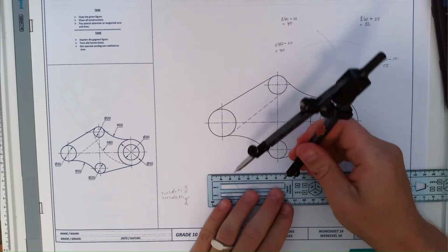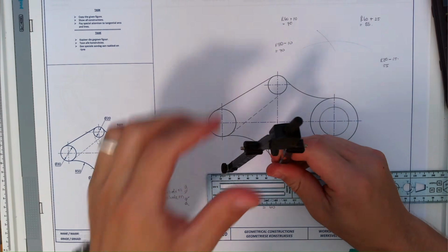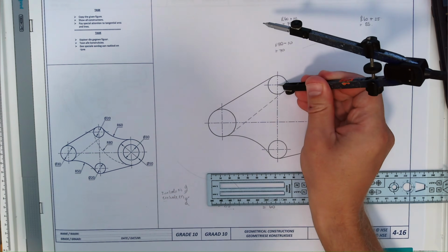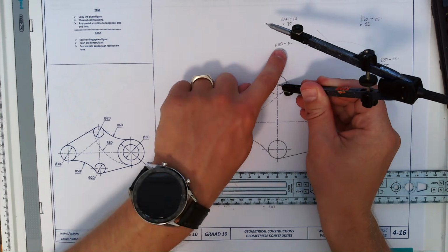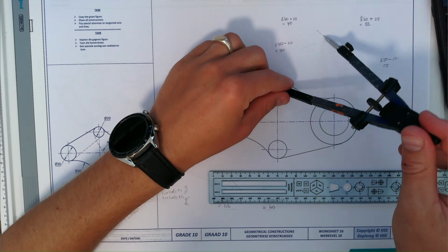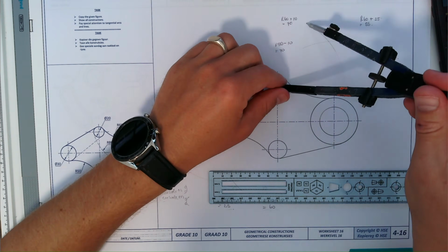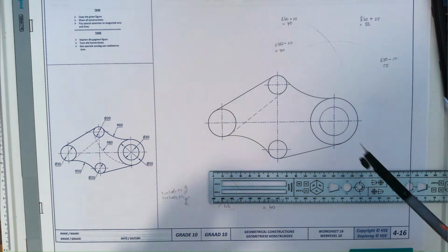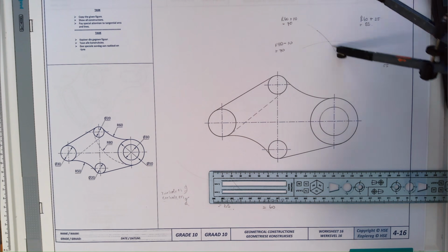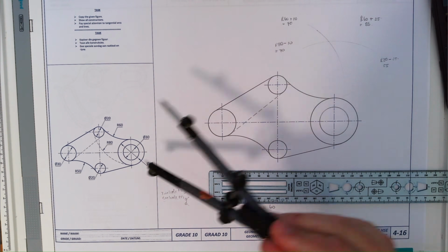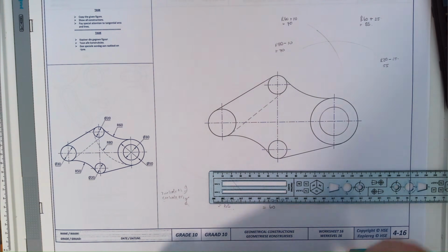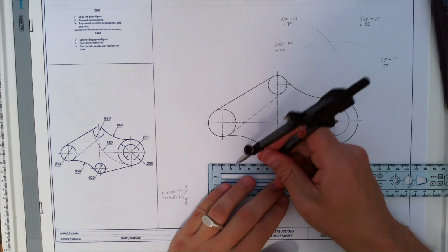So I'm going to take my compass, put that one on 70, in the middle point of the little circle for 70. It is still on that arc. Interesting, it has the same calculation. So on that same arc over there, we are going to get our new point for the included circle. Now I'm going to set it on 55, which we've calculated.